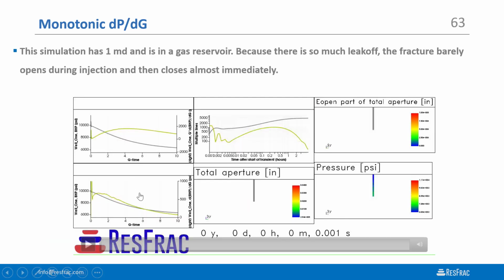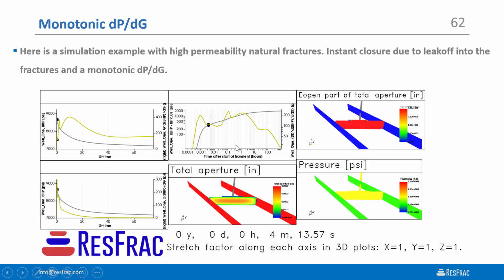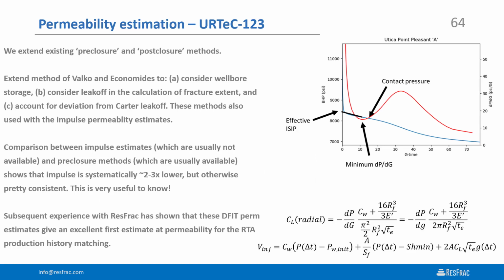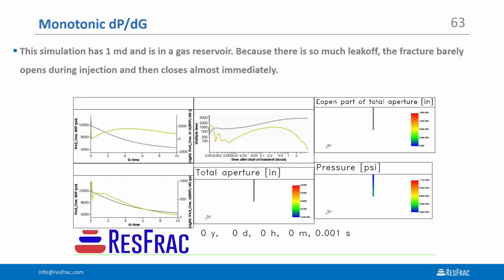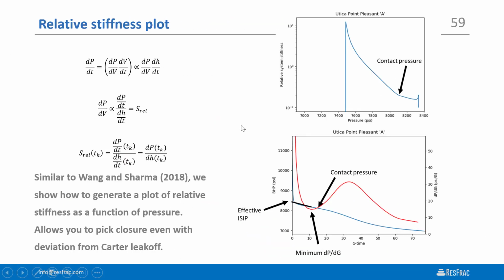That doesn't necessarily mean that we're going to see radial flow at late time, because like in this case here, we have leakoff into these linear features. We might still see linear flow at late time. So that's a challenge. And I think probably the most concerning problem is going back to this problem of near wellbore tortuosity. So remember that near wellbore tortuosity can cause this elevated pressure.